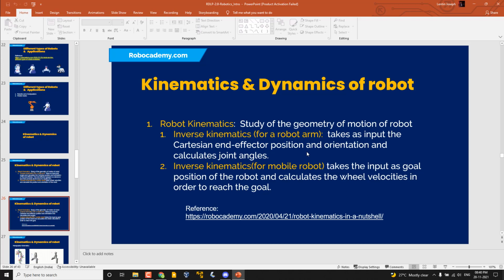If we have an obstacle, then we have to reroute. We feed the inverse kinematic solution to the obstacle avoidance algorithm, which will select the best path that does not have an obstacle. Then the robot will follow the selected path. Okay, understood.